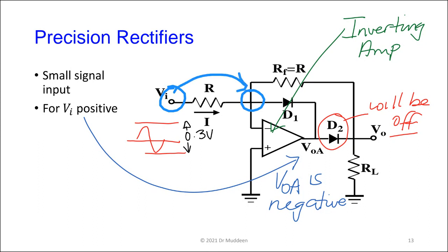But because of the op amp behavior and the gain of the op amp, it tries on the virtual earth, it immediately brings this point down to 0 because we're grounded. So within a millisecond of turning on the op amp, it forces that input to 0.